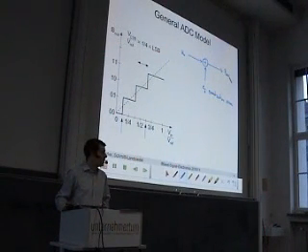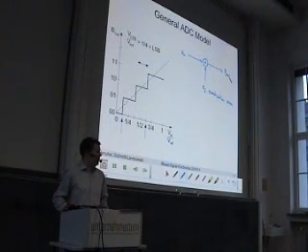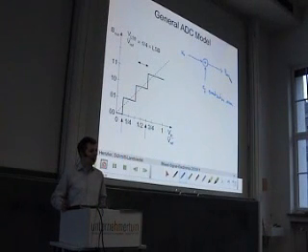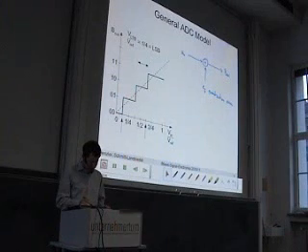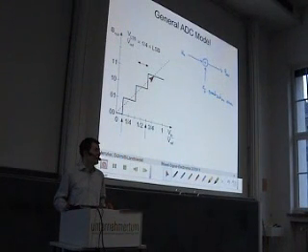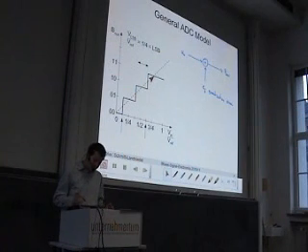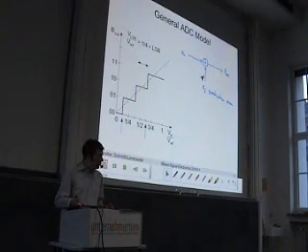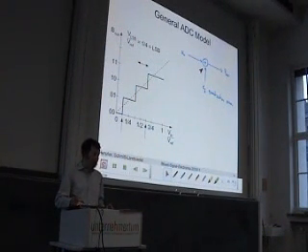Very basic linear model. And if I say linear model, then you can see immediately the problem of this, because if we take a look at the converter characteristics, which is this step function, then we see, of course, this is not a linear device. So the linear model is somehow over-idealized because it assumes that we add a quantization error to the input signal that is decorrelated from the input signal itself.